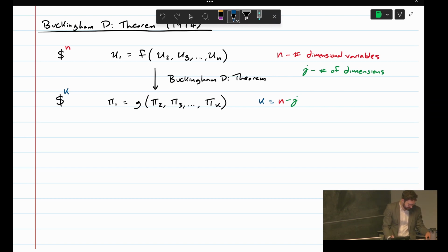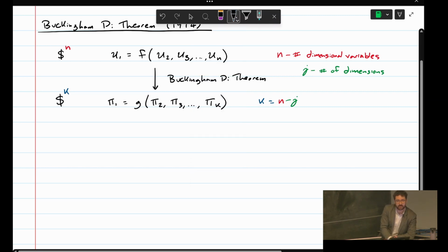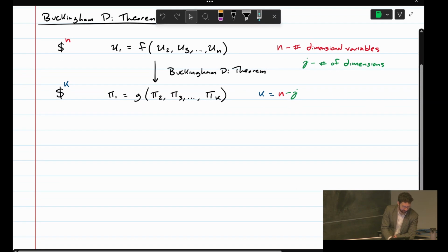So we're going to do a lift coefficient example later on of Buckingham pi theorem. But say the lift force depends on 6 or 7 dimensional variables. We'll see that the lift coefficient only depends on, say, 3 dimensionless variables. So if you want to estimate the performance of something in terms of lift, you only have to measure the non-dimensional variables. So the cost will go down, basically. This is an advantage of doing these dimensionless tests, the reduced cost.